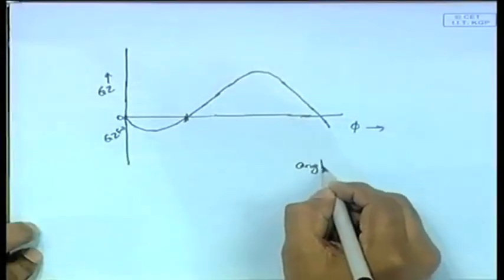Now the ship will remain like this always. So the ship will be going like this always. Okay, the ship will be like this. That is the end result of such a GZ curve. It is of course stable, but it is a strange kind of stability, that is, it is unstable in the region before this. From this region to this region it is unstable, but beyond that it is stable. So this is known as lolling, and that angle is called the angle of loll.